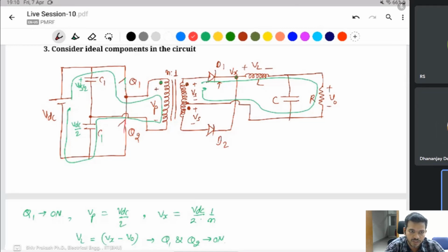If you add a resistance, the losses will increase. That's why you use the capacitor, charging, discharging like that, and the losses will decrease. But in practical cases, a capacitor has an ESR, equivalent series resistance, but it is connected as a capacitor only, two capacitors in series. If they are the same value, then the voltage will divide equally.